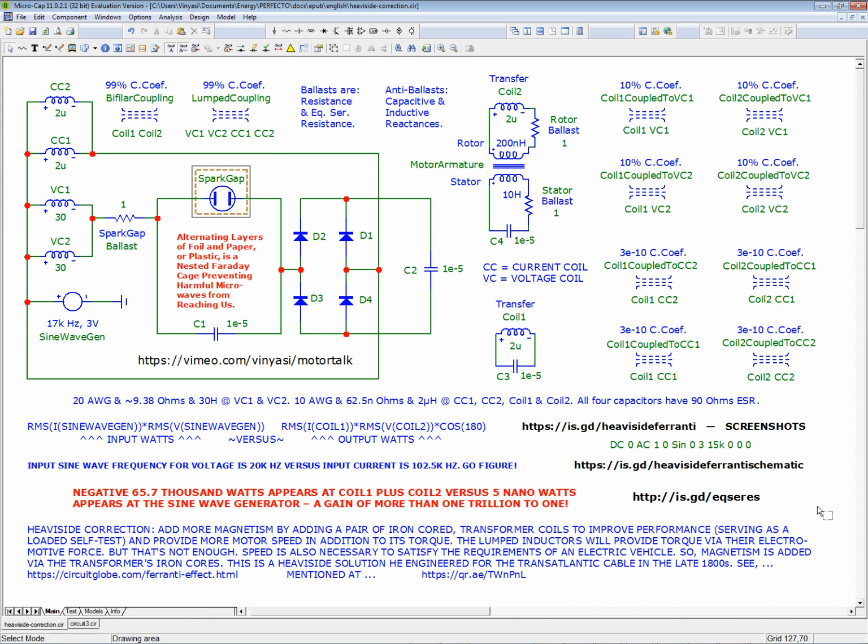And the one I keep getting now, more often than not, the only one that I get that's not an over-unity explosion, is "the time step is too small for transient analysis." Now, in Paul Falstad's simulator, he would say convergence error. He would just come out and tell you. These people are a little roundabout about everything. "Matrix is singular." They don't just say NaN-infinite matrix, which is what Paul Falstad says.